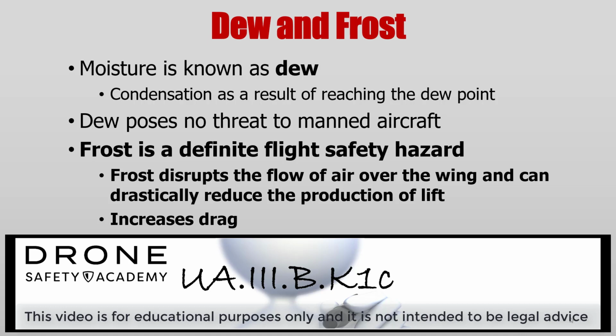However, frost is a definite flight hazard. This disrupts the flow of air over the aircraft and can drastically reduce the production of lift of the aircraft. It also increases drag. So how does frost develop? Well, we need moisture and we need freezing temperatures. Pretty easy, right?